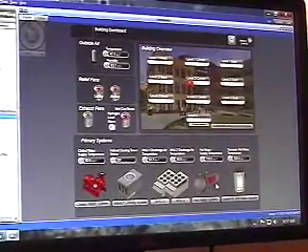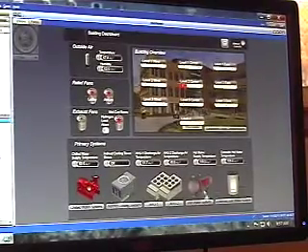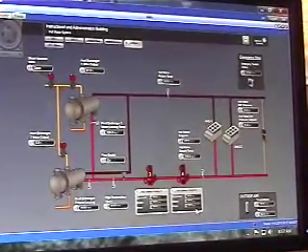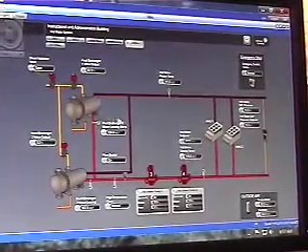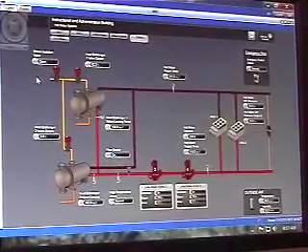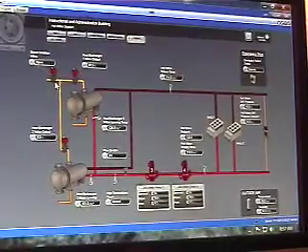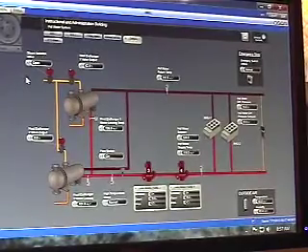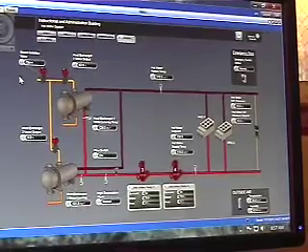Here's your hot water system right here. You can see right here that it's running, moving hot water through the coils. Click on this. You have 2 different heat exchangers. So whenever the system's enabled, the steam isolation valve opens up, which allows hot water to flow to either one of these heat exchangers. This isolation valve right here is set so whenever the system's disabled, it'll automatically close, or if somebody was to, in an emergency, hit the break glass button, it'll spring return close and shut down.